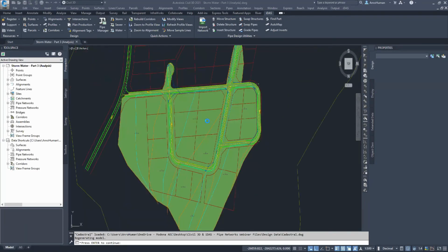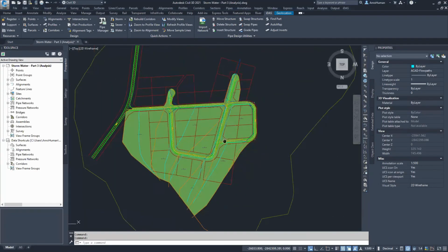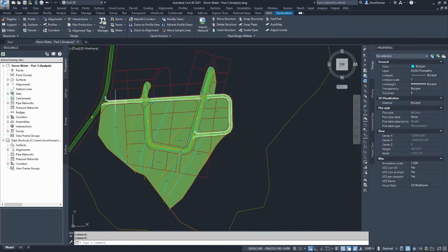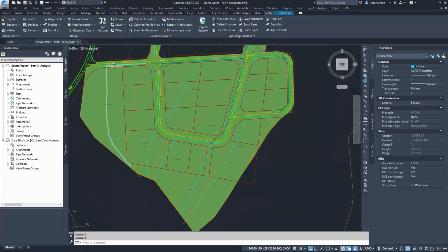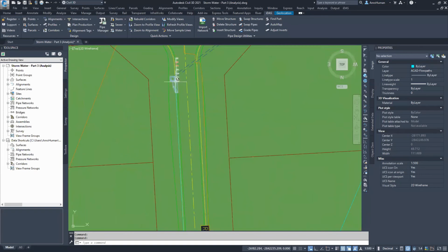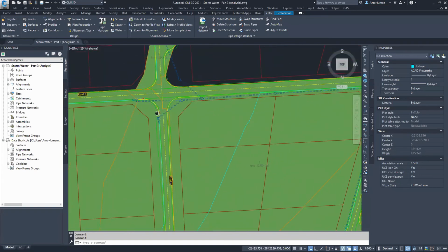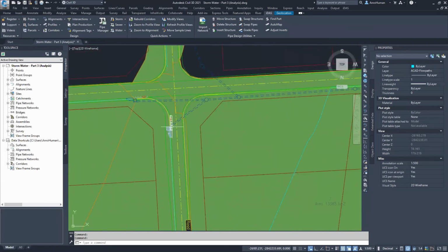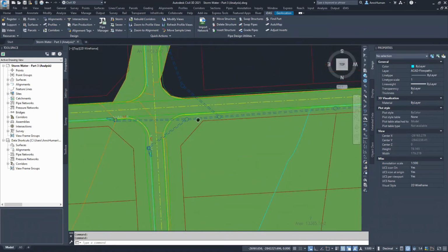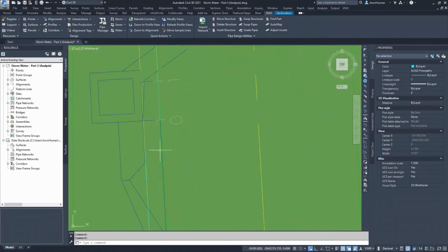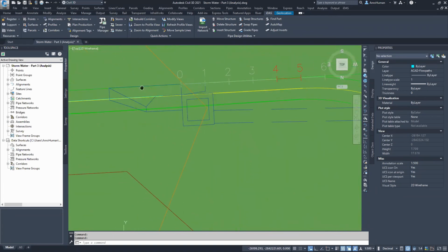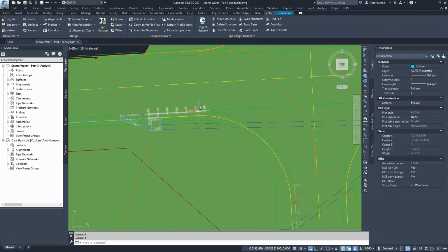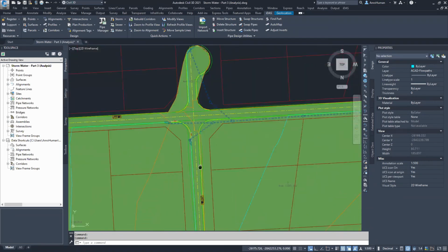Okay, so this is my analysis drawing. Basically what I've done is I've drawn out all of my parcels from my watersheds. And these blue lines are my longest flow paths for each of these catchments. My grid inlets, I've already rotated all of these grid curb inlets to sit correctly and to sit as close as possible to the curb lines and to sit within this little red part over there on the measuring stick.